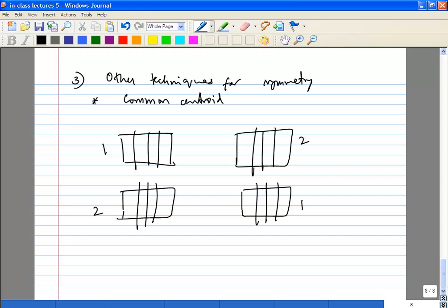It's quite common. Now the only thing you have to be very careful about is this is very layout intensive, because let's say you had to connect out these gates. Now you have to route the gates, you have to route the source and drain connections. So it's actually very intensive. And I would say in RF layouts, it's only of limited value. But like I said, there's always an exception. You may find a case where you might want to use it.